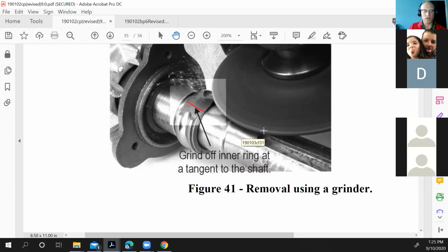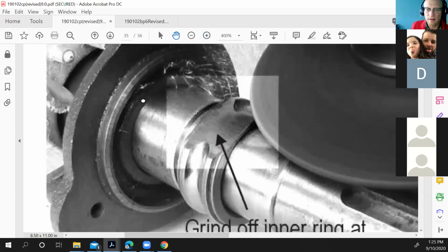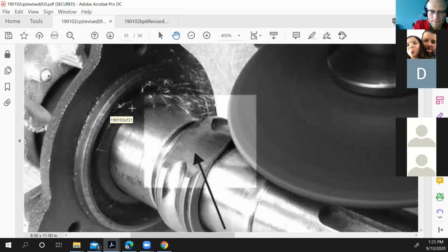My tips for using the torch when you're cutting this thing off is work fast and only put the heat where you want to cut. So what you can do, if you work quick enough, you get your torch and you start right, I'm gonna make this way bigger. You get your flame, you start right over here. As soon as this turns red hot, you hit the oxygen to it and it's gonna start separating apart and blowing apart. And you just move backwards, nice and steadily, and you will see the cold steel underneath as it starts to open up.